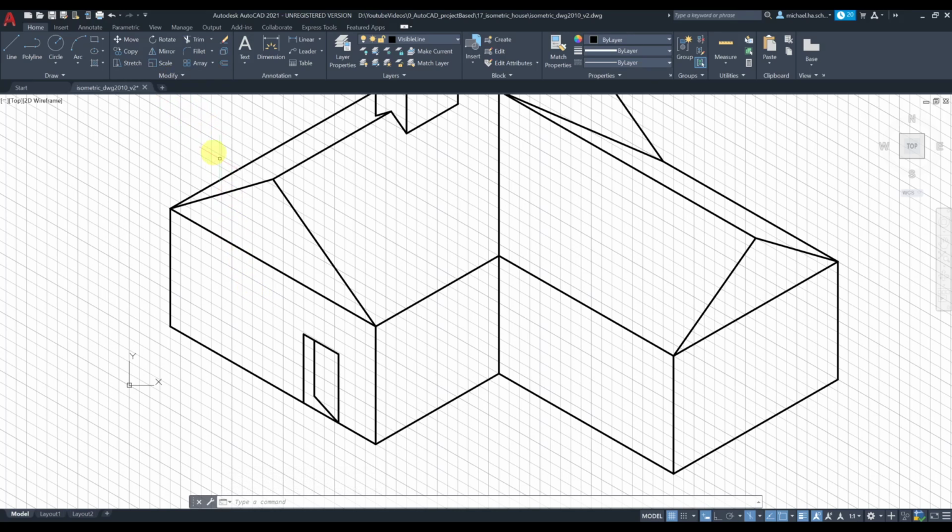One thing I'm going to show you is ellipse with Isocircle. So in isometric, to draw a circle, we actually use ellipse. This option wouldn't give you that isocircle, but either one of these will give you isocircle. Or you can just simply type here EL for ellipse, press enter, and as you see, Isocircle is one of the options. I is highlighted. You simply type I for Isocircle, press enter.